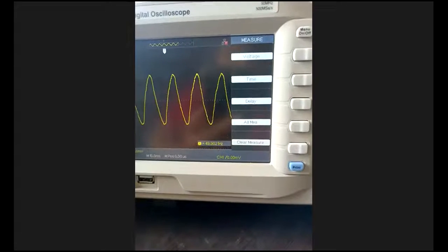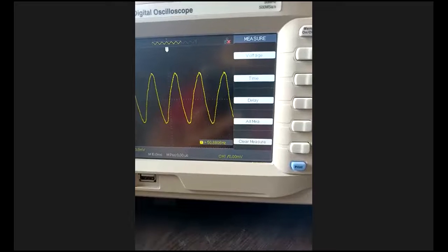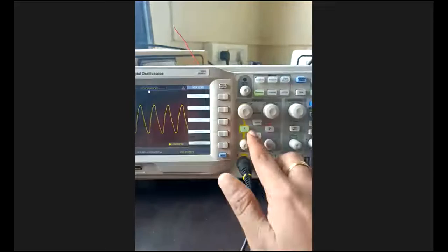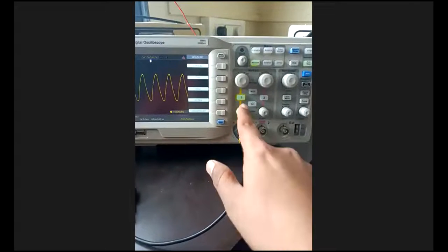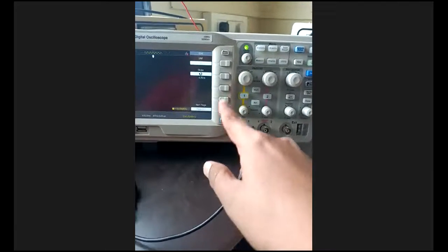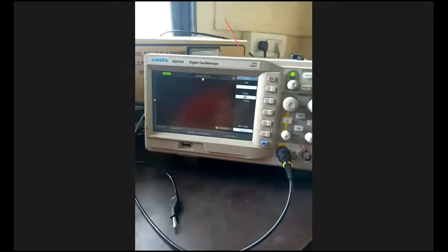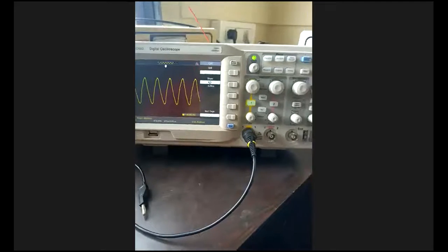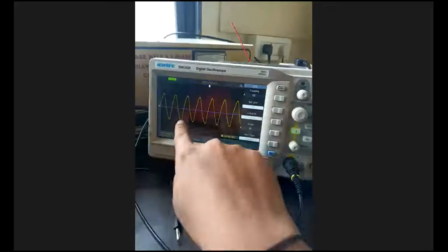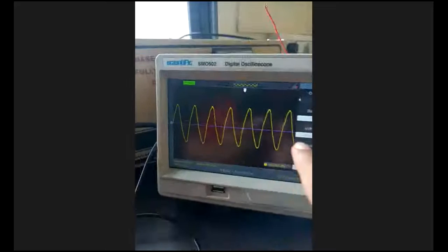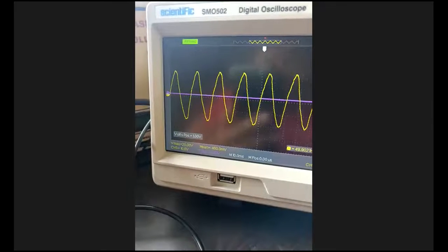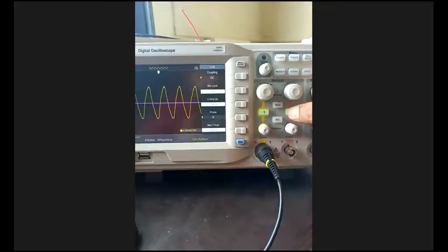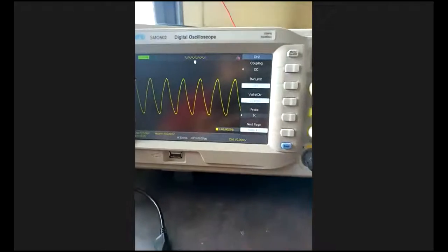What is it showing? Voltage, time, delay, all measurements. Yes. Okay, see here, I told you the probe is connected to channel 1. If you press it like this, it is going to trigger or turn off. It is nothing but display again. Now we have to trigger channel 1. If you press channel 2, see, the reference line came here. We can take this as a reference. So I will not take any reference line. I will cancel that. Only channel 1 I have set here.